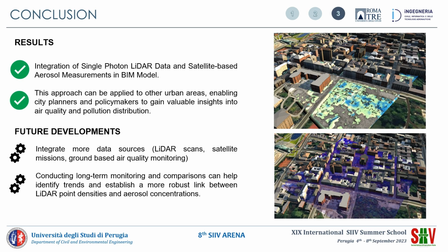The study successfully demonstrated the potential of using single photon LiDAR data in conjunction with the satellite-based aerosol measurement for assessing air pollution in urban areas. The correlation between point density calculated from LiDAR data and aerosol data from the Sentinel-5P satellite suggests a possible link between LiDAR point density and aerosol suspended in the air. While the results are promising, it's important to acknowledge that the study only points in that direction, and further research is needed to establish a more definitive relationship.